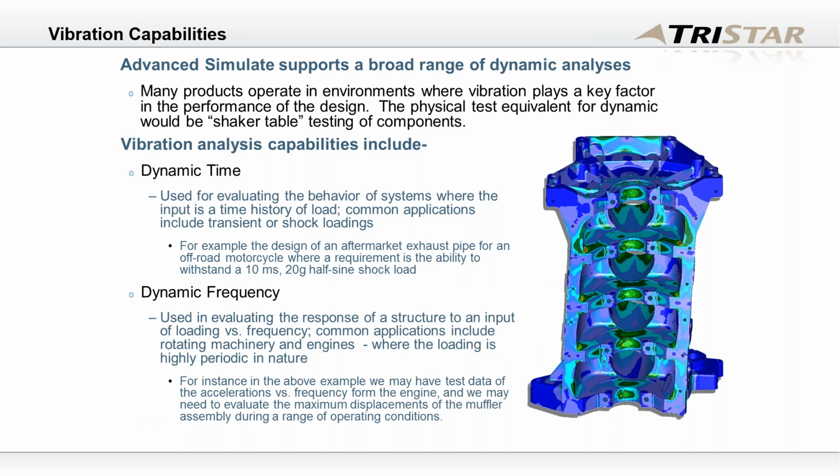Some of you may want to mimic the real world shaker table test inside of Creo Parametric, and you have an assembly or a component. Maybe they're asking you to do a half sine sweep test, right? That they do in the auto industry, that's a huge thing, right? You could just mimic the real world shaker table test by applying a time dependent load, a frequency dependent load.